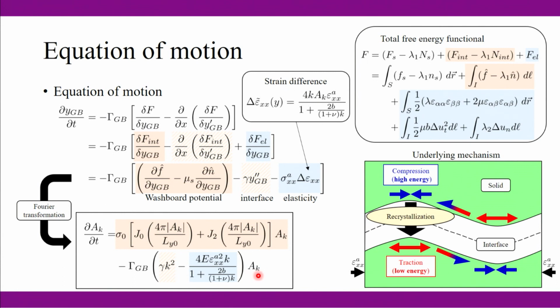One depends on wave number, that's generally something we expected, because the elastic energy or the surface energy difference will depend on the wave number. But there's something that depends on the structure, right? It depends on the coincidence site lattice structure, and that contribution should only depend on how big the amplitude is, or just saying where your interface is, right? What kind of structure it goes through.